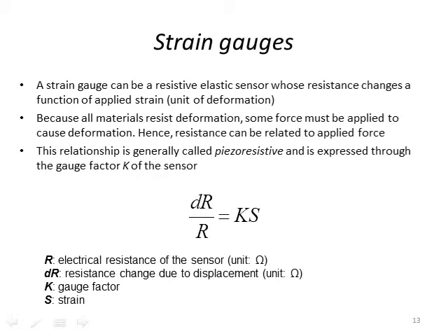Now, we can also use strain gauges, and a strain gauge, in this case I will describe essentially a conductive material that has a finite resistance, and as the material, which is elastic, as you bend it, for example, the resistance is going to change. And this is called a piezo-resistive effect. So when you strain the material, the resistance is going to change, and then we can detect the displacement based on the amount of strain.